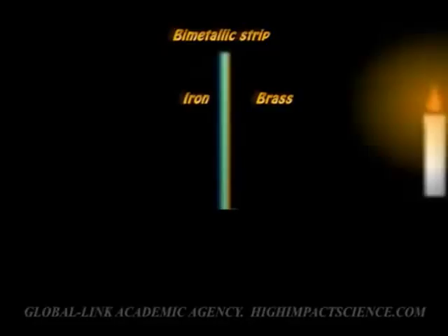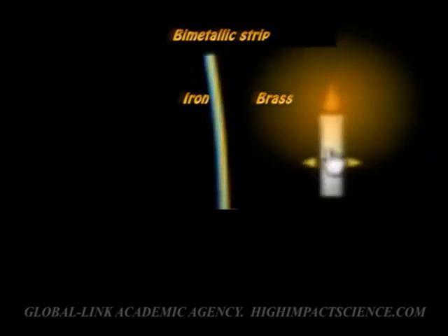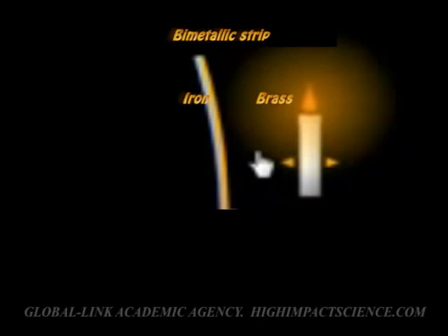The bimetallic strip. When two metals of different linear expansivity are riveted together, they form a bimetallic strip. Brass and iron are commonly used to make bimetallic strips. On heating the bimetallic strip, brass expands more than iron. The brass thus becomes longer than the iron for the same temperature range. Therefore, the bimetallic strip bends with the brass on the outside of the curve.